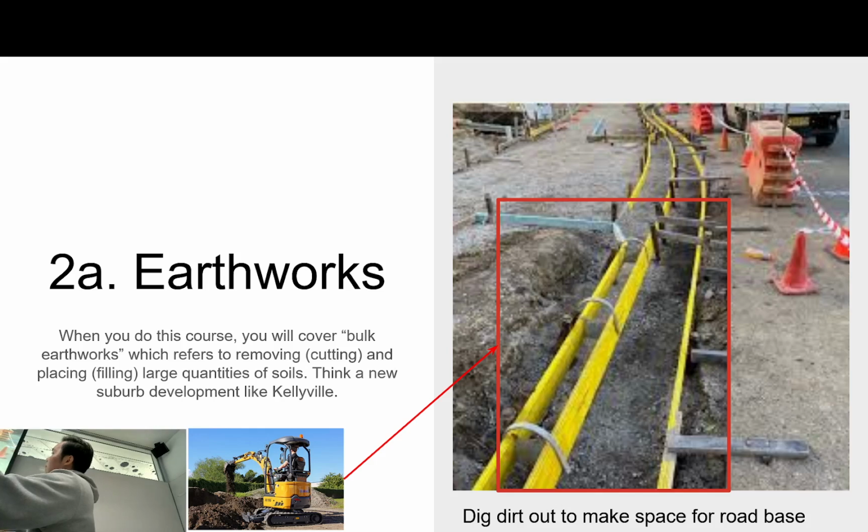Now, in terms of the earthworks that you're doing here, as I said, you're removing some of that back part, your topsoil, and you're removing a little bit of that road, okay? And the reason is, when we are actually putting in the formwork, you need space, right? You need space behind and in front, so you can actually put it in and form it up properly, right? Imagine you just cut out that concrete bit, you wouldn't have any space to put this wood, right? Because let's say this is a 600 mil section, that is already 50 mil, for example, you're not going to have it correct to spec, right? So you actually need to dig out a little bit more so that you can put it in.